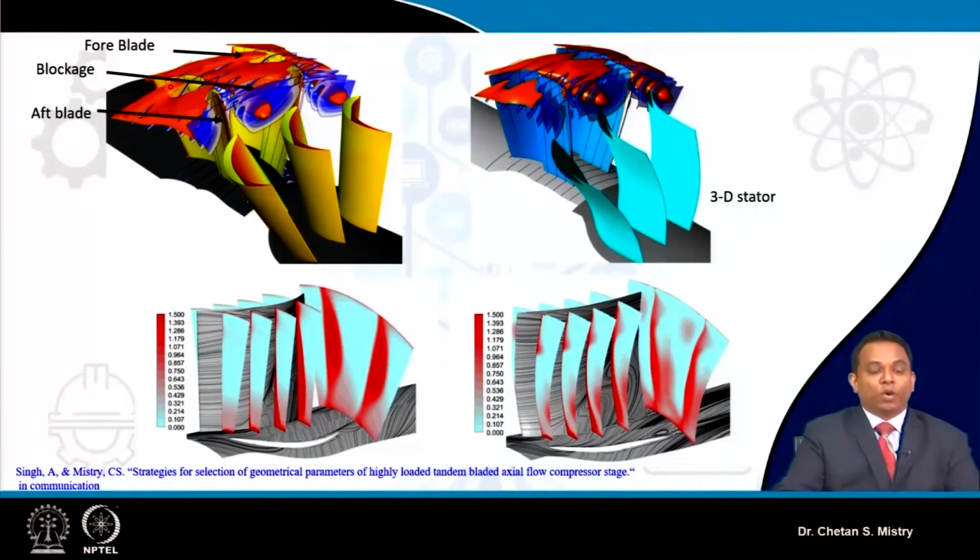So in terms of the flow structure coming out of this tandem rotor, we can say it is making a blockage to our flow. Now this blockage will be striking the next stator. In the region where this blockage flow strikes, that will lead my stator to work under off design condition. That's the reason why the flow coming out from the exit of the stator will have a different kind of flow structure.